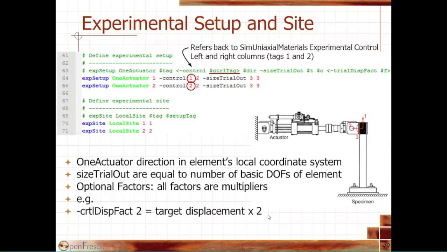And then we can do the same thing with all the measurements that we're taking. These will be the DAC values, anything that we measure, displacement, forces and so on. We can modify those too. If, for example, we send out twice the displacement, we should probably take half the displacement of what we measure when we send it back. So we would say DAC displacement factor is a half. Every one of these factors will always multiply whatever your response quantity is by the factor.